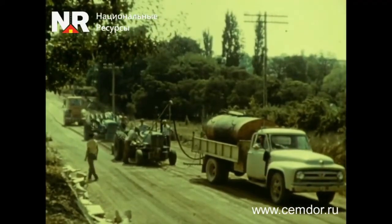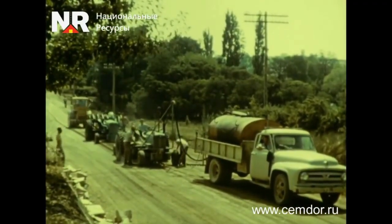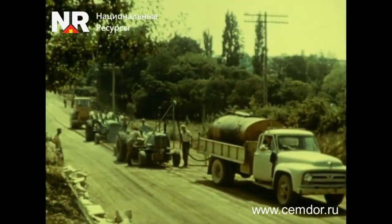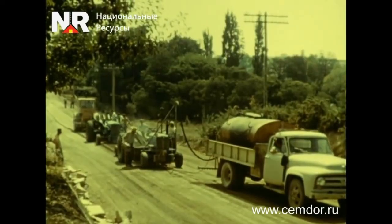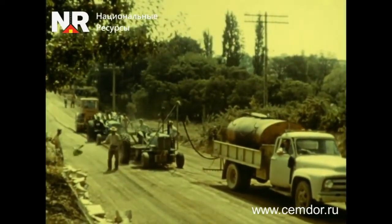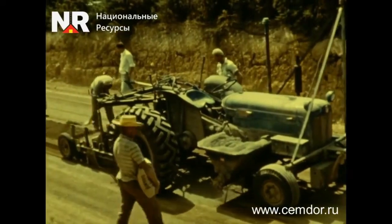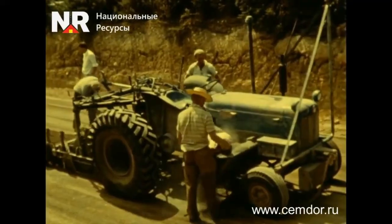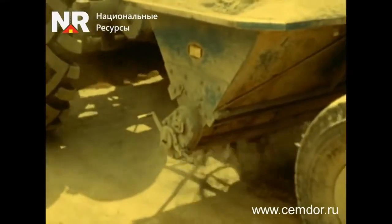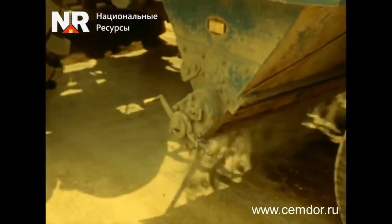Equipment designed to carry out the entire stabilization process in a single pass is known as a stabilization train. It performs crushing, cement distribution, mixing of the soil-cement mixture, and compaction. The first unit of this mechanism is the cement spreader, which evenly distributes cement over the surface of the constructed layer with the required amount determined through laboratory tests, based on the sample of the soil being used.